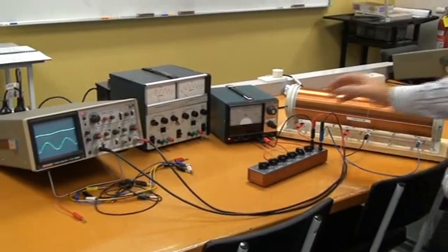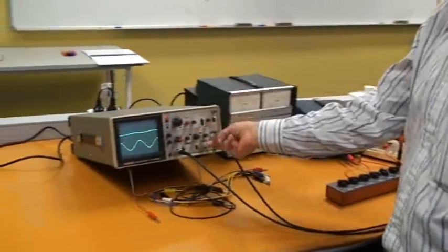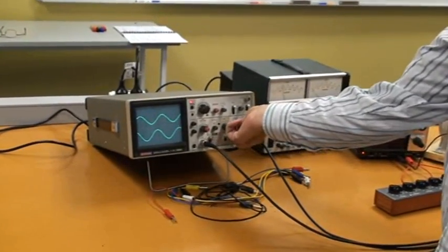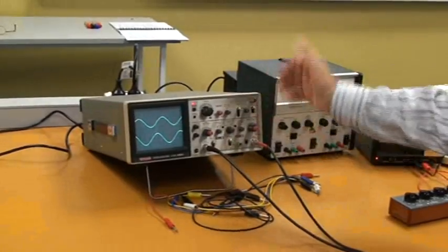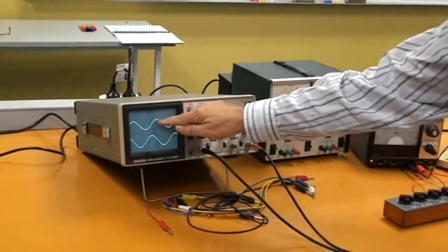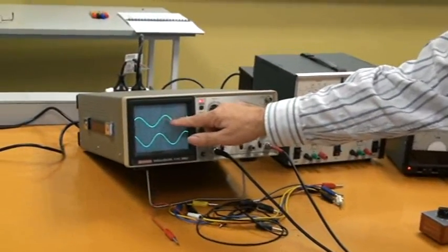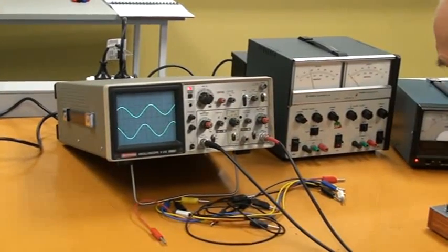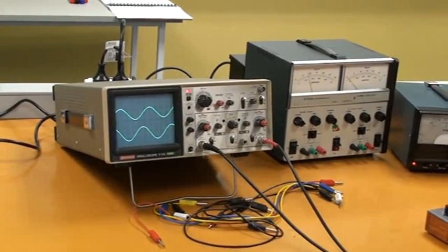And then again we take our readings. Now we haven't changed the resistance value, so we don't expect to see any change in that. And that's still going to be 2 volts. So it's 2 squares times 1, 2 volts. But we've got a different value now for the voltage across the second coil. This is VL2, you might say. And again it's 2 squares, but now it's 2 squares times, I think it's 0.1. So we've got 0.2 of a volt.